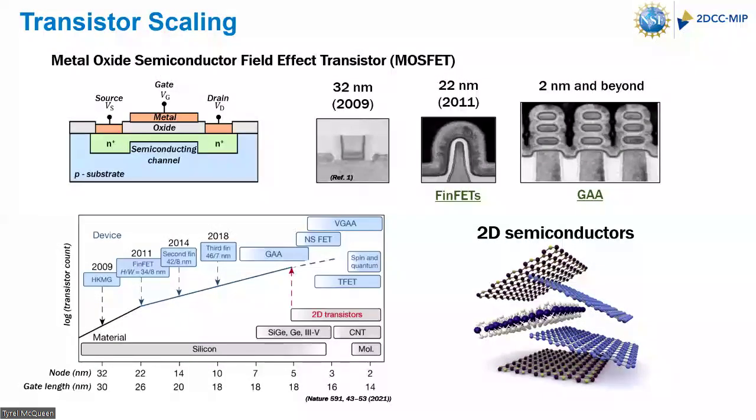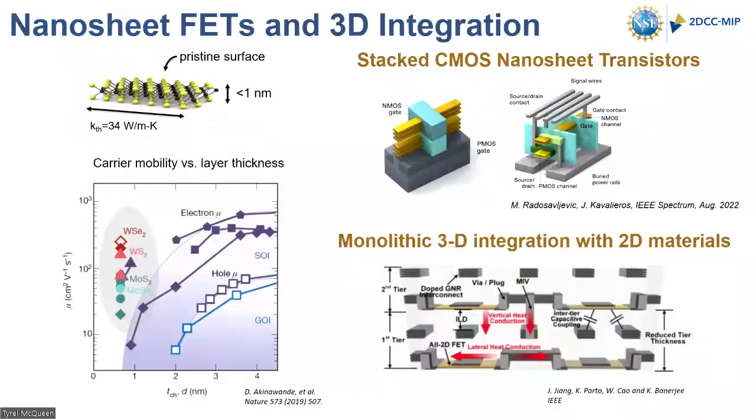So as I said, this is where 2D semiconductors come in, right? So they're another material that's being considered for future generation gate all around or nanosheet FETs. And the reason why is because there's some really compelling properties of 2D semiconductors. The first and the most compelling property is that they're nearly atomically thin, right? So something like moly disulfide, if you're just talking about the monolayer, it's only 3 atoms thick, right? It's nearly the ultimate thinness. Ideally, maybe you just want a single atomic layer. But moly disulfide is pretty close, so it's really thin.